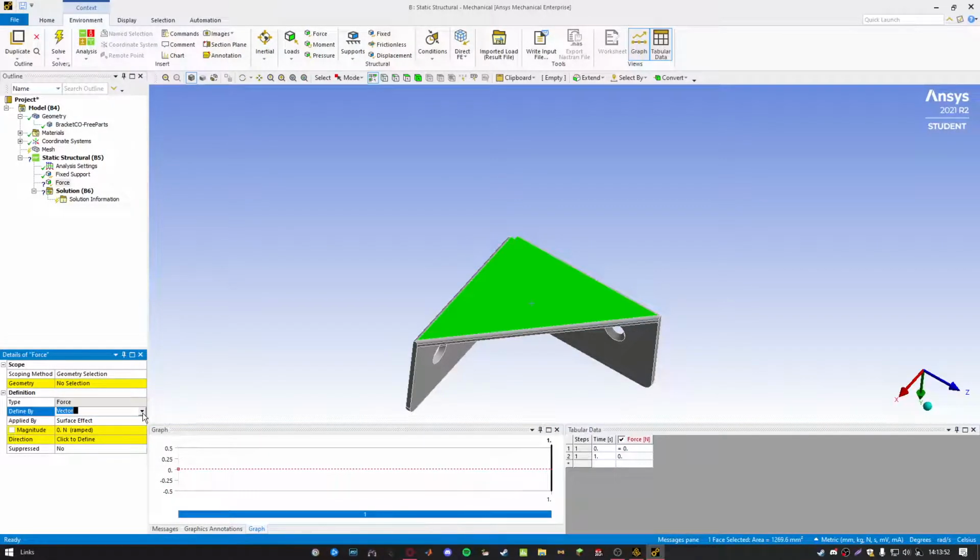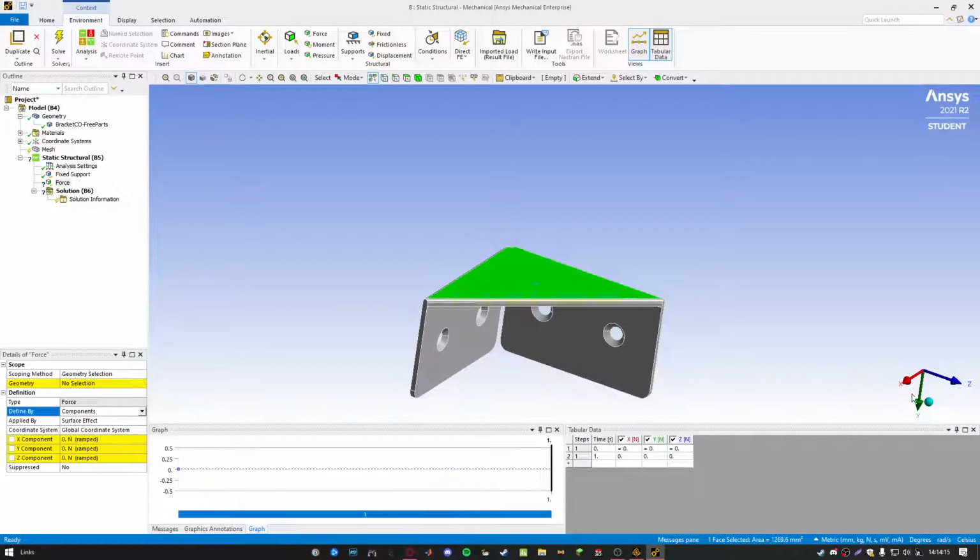Or what I did is you'll basically put a distributed load over the top, which is probably what you'll do as well. But for something like Miko's scenario where he's pulling back a bow, you'd put a vector force and set it to just one axis. So in his case, it might be the z-axis that you'll set the force in. But we want a component, so our component will be the y component because our vertical axis for our part is the y. So we'll go here and convert whatever force you think is going to be displayed on here.